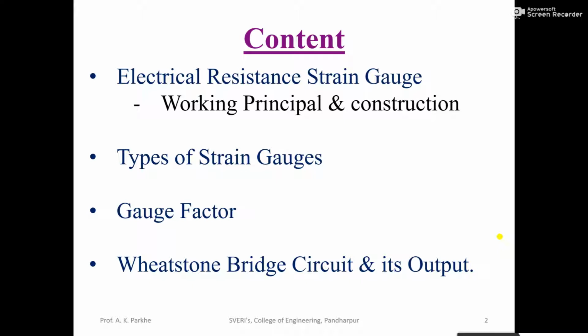And then we'll discuss the Wheatstone bridge circuit and its output. Wherever we are using strain gauges in any type of application, we have to use the Wheatstone bridge circuit. That means if we are using one strain gauge, or sometimes two, or sometimes three, four or more strain gauges in a single application, at that time we have to use this Wheatstone bridge circuit to calculate the output of all those